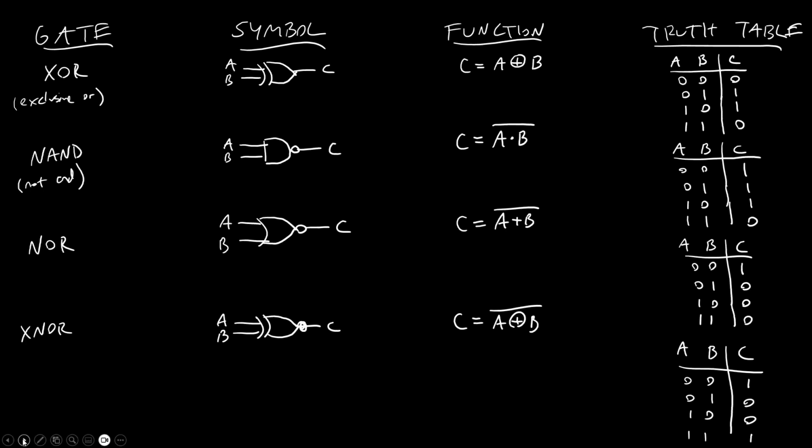Say you wanted to build a circuit to turn on an LED, only if a certain combination of buttons are pushed. We showed earlier in the video how you could do that just by hardwiring buttons or switches in series with or parallel with an LED to represent AND or OR gates, but say you wanted to do that with an actual AND logic gate where the output is going to be connected to an LED with a current limiting resistor.